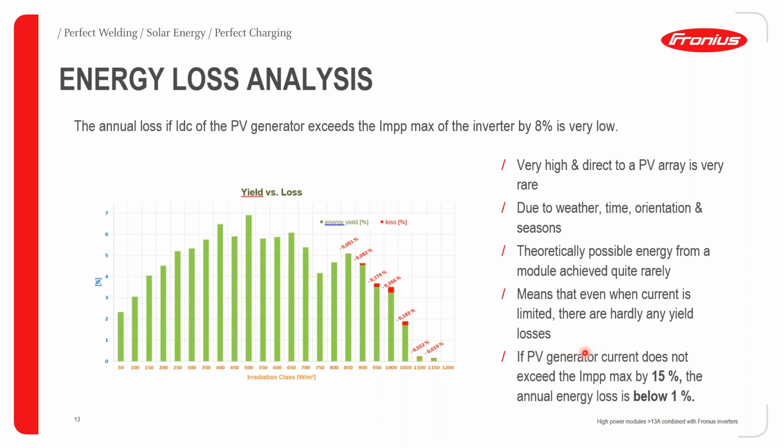Remember also that it's possible to oversize all Fronius inverters by a factor of even 50% in some cases. And therefore, when you do oversize an inverter, you already are increasing the connectable current on the DC side, but that has no effect on the inverter warranty as far as any issues caused by the DC connection.